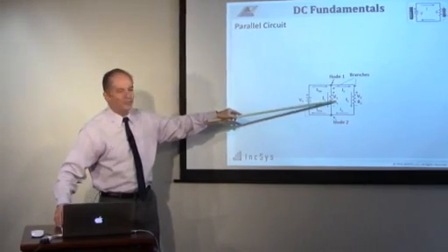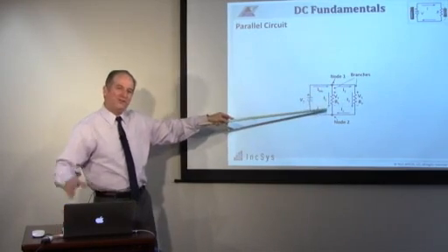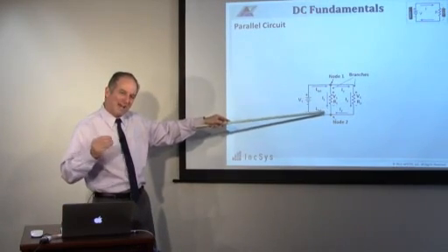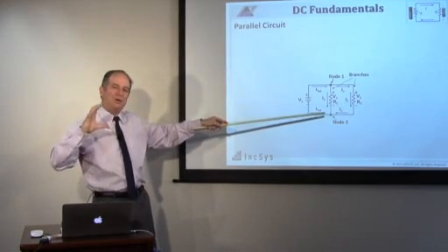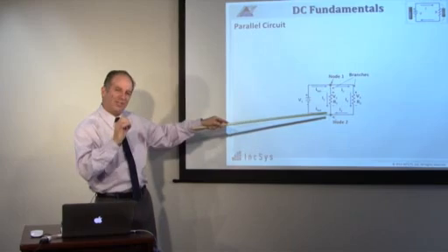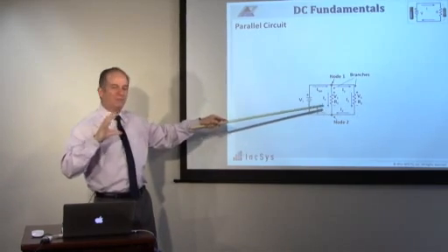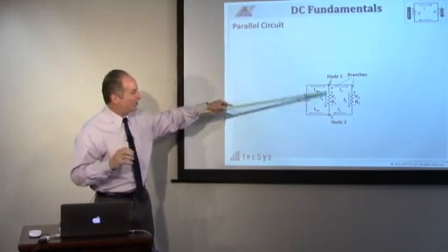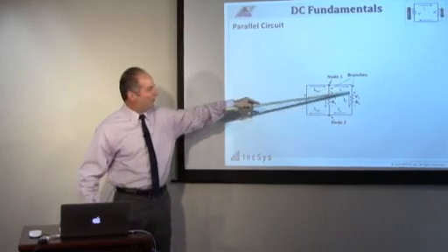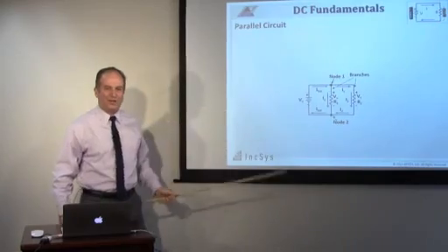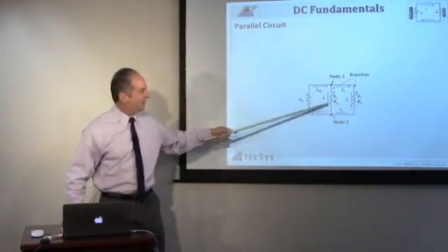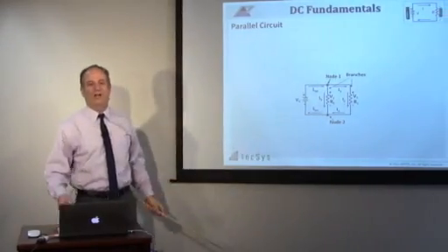The resistor with the smaller resistance is going to have more current flowing through it. Remember, a bigger pipe has less resistance for water than a skinny pipe. If we have less resistance, we're going to get more current flow. So a high resistance is going to have less current flow than a resistor of lower resistance. If they're both the same, then I1 equals I2.